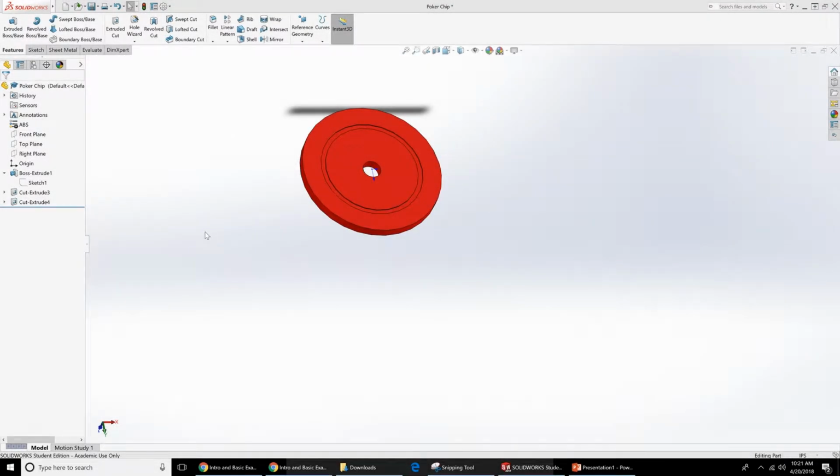Okay, so for this project, our group chose mold tools in SOLIDWORKS. The purpose of mold tools is to create a mold from a part you modeled in SOLIDWORKS. It creates the core and cavity of the mold. The core is the half that has extended surfaces, and the cavity is the half that has depressions in it.